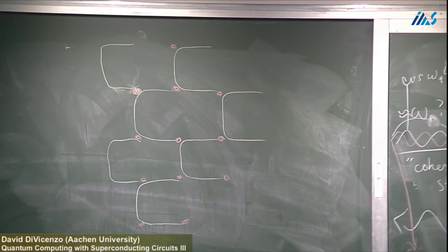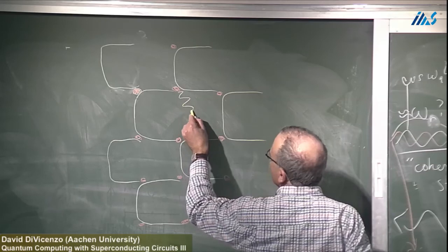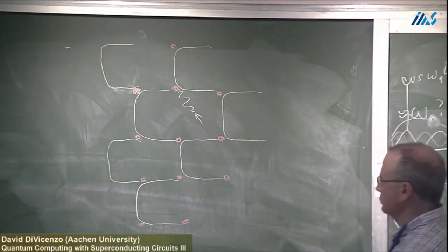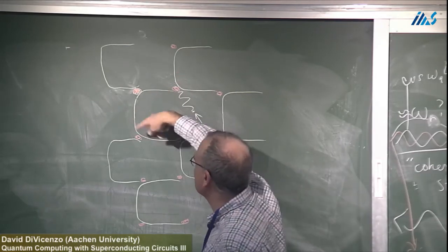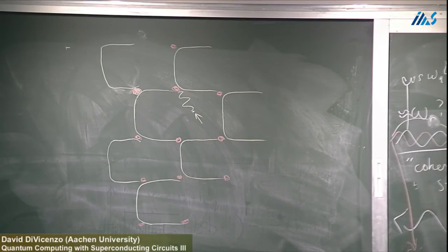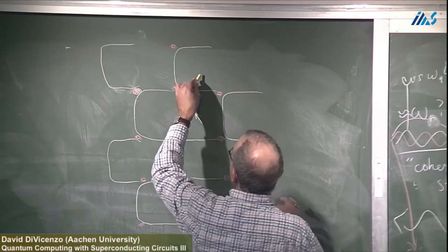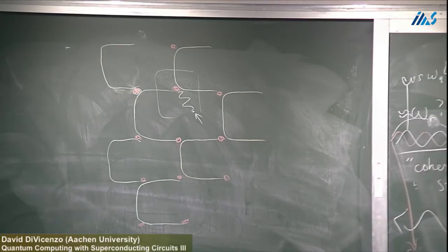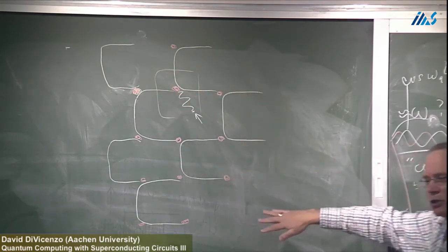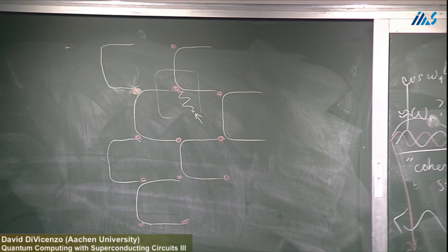One fact, and actually already presently explored, is that measurement can in fact come in from a completely different cavity, and it can be done in reflection also. So just one extra cavity tuned up to be just the right parameters to be a measuring cavity is actually a good thing, rather than double using these cavities for both measurement and for coupling. But the main difficulty is that in each square element of this, you have several inputs and outputs that are needed. You have to do 1 qubit gates, 2 qubit gates, measurement. And so in this area, if you have your 1,000 qubits, as John Martinez has announced, you need thousands of input and output channels of wires, each of which in present day experiments involves its own devoted coaxial cable. So you have to think of this bundle of coax cables. And to me, this starts sounding like some CERN experiment. It has to get simpler than that to go really a lot further.